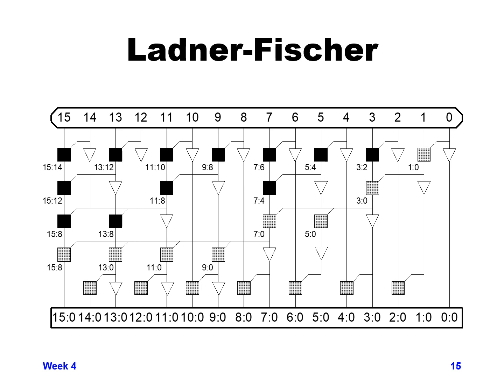But you can see the number of wire tracks is minimized, and so we're not changing the minimum wire tracks, but we have a little bit more as far as logic levels. We have more logic levels than the minimum, but we don't have as much, but we have a little bit more fan out in order to balance between those. So in this case, we're balancing between the Sklansky design and the Brent-Kung design.